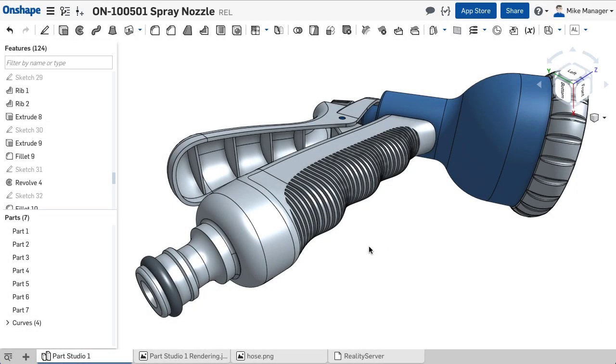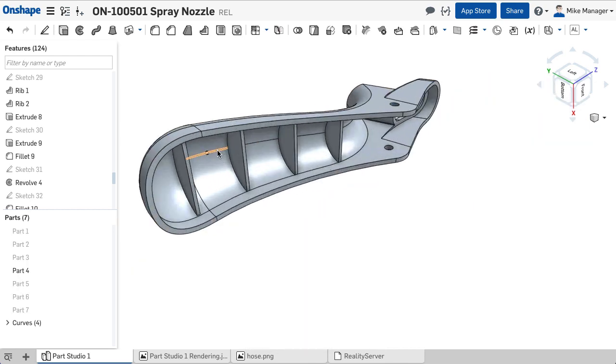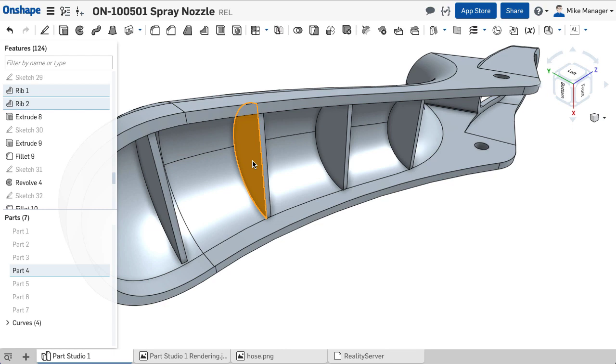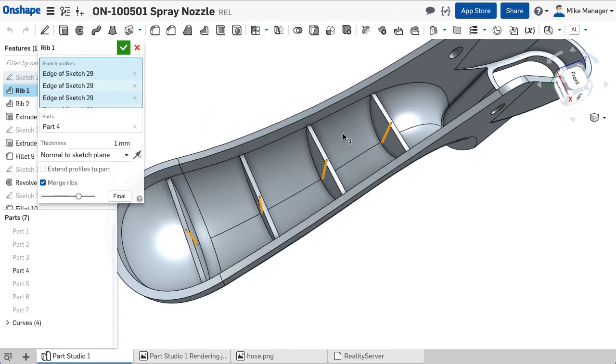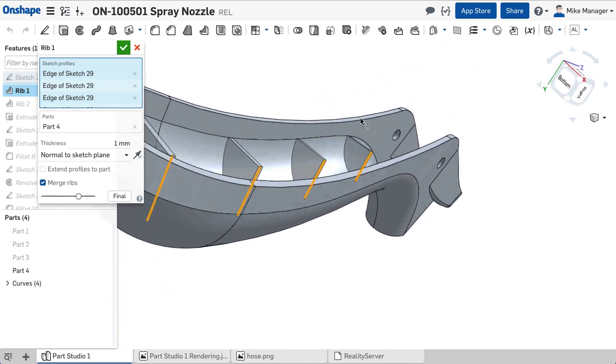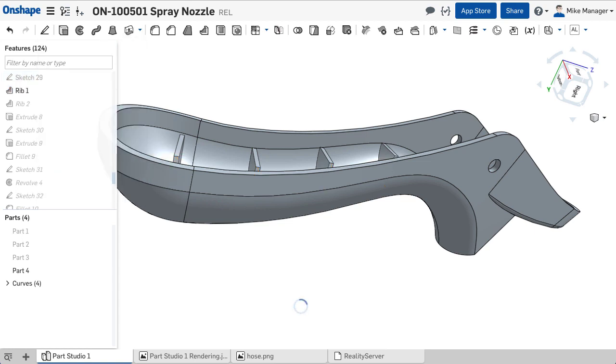Ribs are used to generate thin-walled support structures that are popular in both plastic part design, as well as cast, forged, and welded structures. The rib feature is a sketch-based feature that requires sketching elements to be created in advance of using it. There are also two direction choices when designing a rib, parallel or normal to the sketching plane. This is important to consider before setting up the location of the sketch that drives the rib.